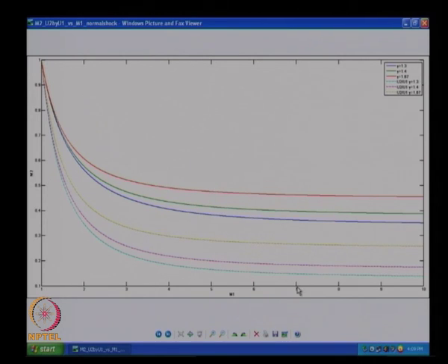If I go above Mach 7, that is more valid; it is better if it is Mach 7 and above. If you want, you can call it above 5 itself, and u2 by u1 again is almost a constant after that point. We can actually find a value for the high Mach number approximation, which is what we are going to start with today. So now we will go to the board and find the asymptotic values for this.